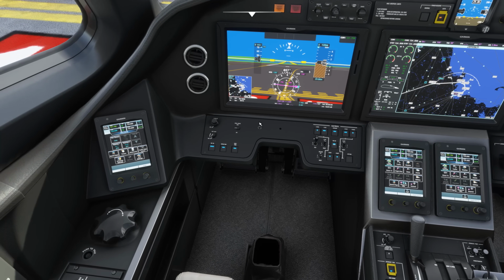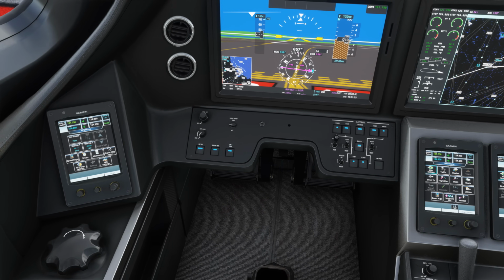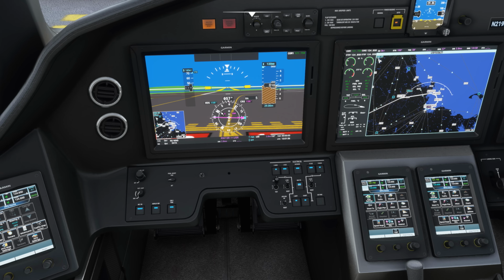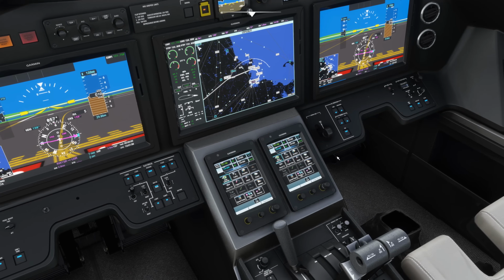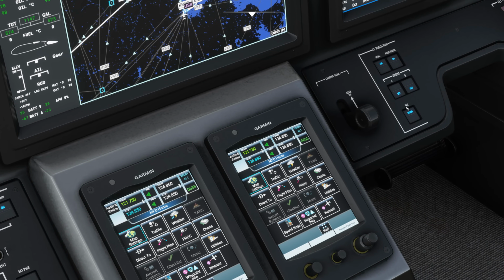Well, actually, you know what? I just realized that we don't have the weather. What did it say? We can check. Oh, it was 10 degrees. So actually we will want anti-ice. Disregard that. Let's put some anti-ice on. So we'll throw the anti-ice on. Pitot heat, definitely. And then left and right engines we'll throw on as well.